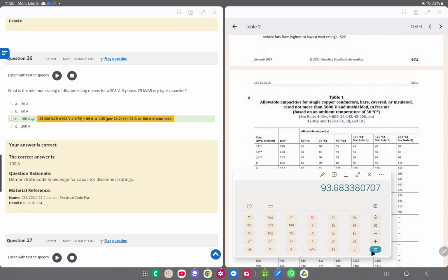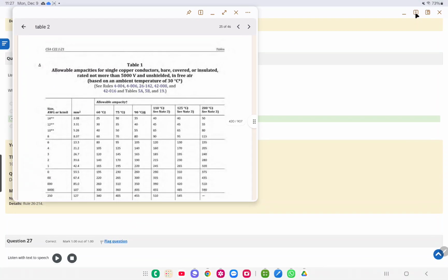And if you go to table 13 and you see that it's in the range, then you would stay with 100 amps. So capacitors, hermetics, motors: if you're in the range, you size down, pretty sure. Let's check it out.